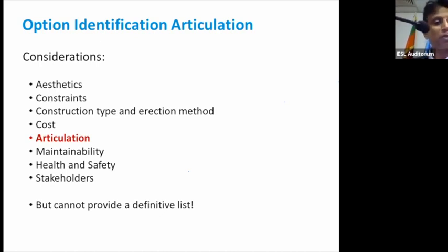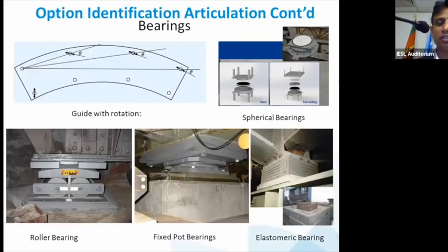So you have to provide what do you call these things, bearings, right? Which is a very important aspect, because don't think these are a piece of rubber. I talked to an engineer and asked why he was worried about it, as it's a piece of rubber. But that's not the case, because the elastomeric bearing, the one at the right, has certain steel plates inside. There's a certain way of designing it, because you need to facilitate that movement, right? The size, everything matters.